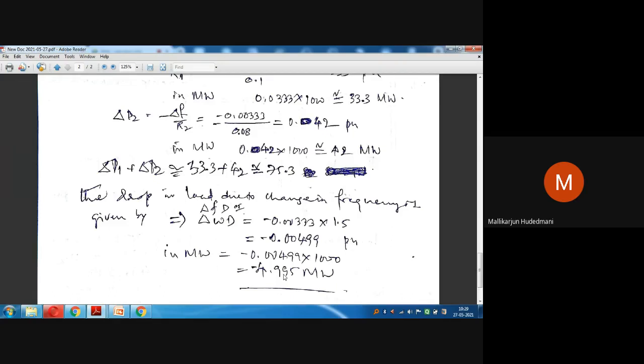What will happen to the system? Definitely load relief is experienced by the power system. By the relief of load directly, what is your observation? Directly frequency shoots up. Delta F, what I am calculating here is on loads 50 minus whatever the quantity in this example. It may become 50 plus that extra quantity.